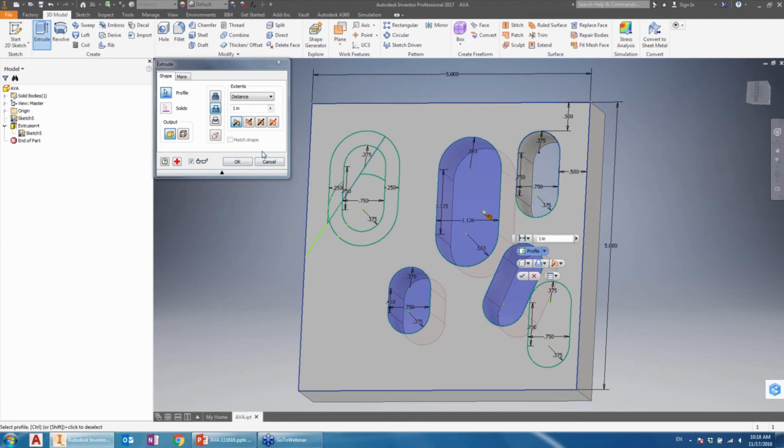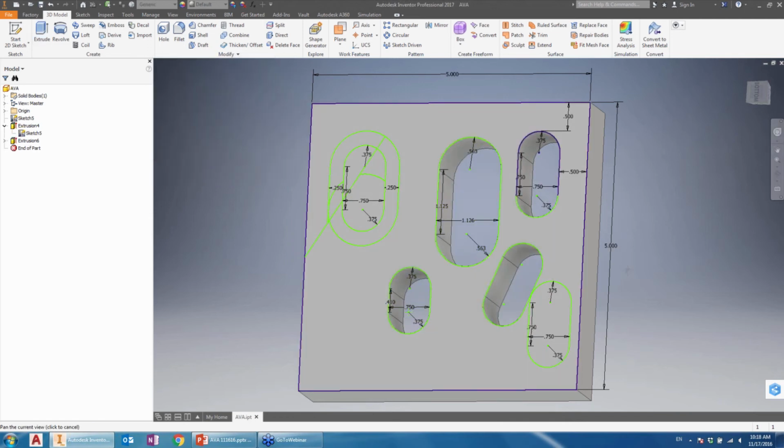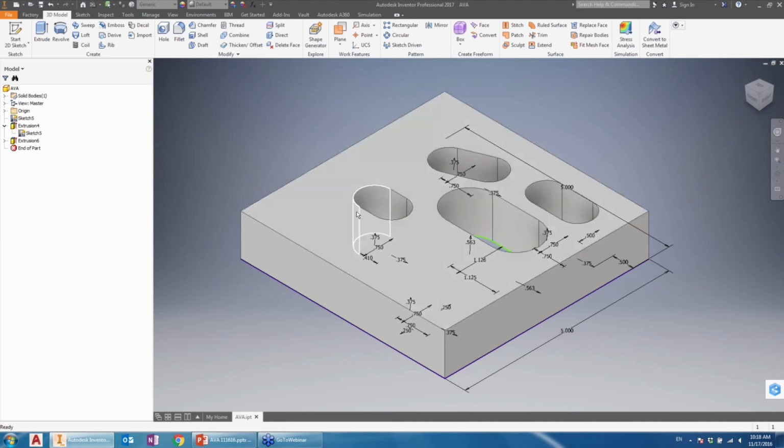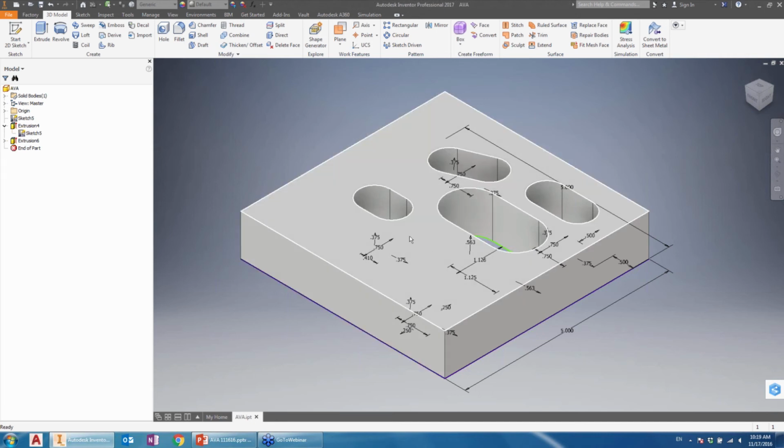I didn't have to do any reference geometries. I didn't have to, yeah, things like that. So it can save you time if you want to share sketches. This is a very quick and easy tool. If you guys aren't familiar with it, I recommend using it. Not only in these cases when you want to go back to sketches, but also when you have to create several features off of the same sketch and they're not the same feature. You want to use the share sketch ability.